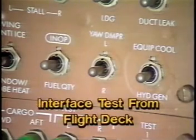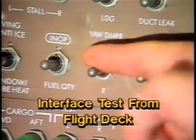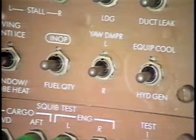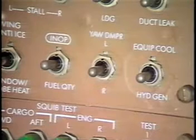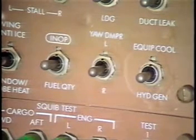To perform the IRS interface test in the flight deck area, move the yaw damper test switch to the left or right position. This action places all three IRUs into the interface test during the time sequence of the yaw damper test. The test lasts about 12 seconds.